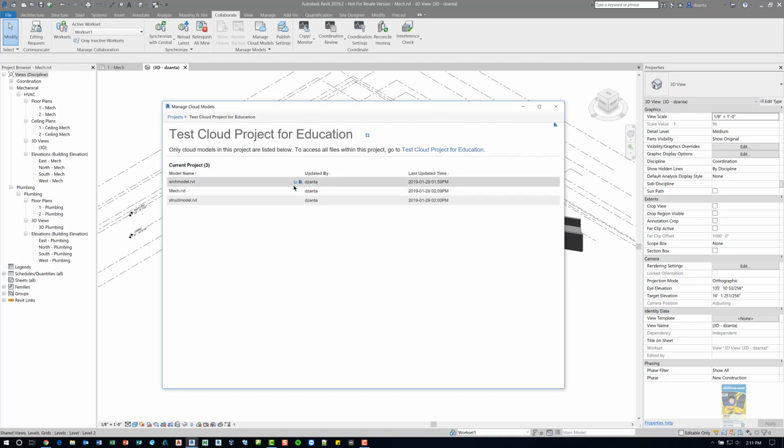So I can at any point in time put my mouse inside the line item and click Publish Latest if I need to. What's going to happen is this. Revit is going to take your existing model that you told it to, grab all the data that's necessary to make that model, grab all the views and sheets you told it to publish, and it will publish it up to the web, to the cloud-based interface, so that those stakeholders that you have invited to your project who don't have Revit can actually see the Revit content that was published at that certain date and time, and basically just get a good timestamp of what's going on.